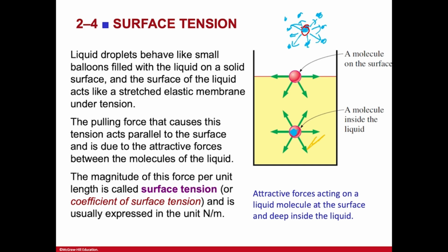So as a result, if you try to find the net force acting on this fluid molecule, what will you get? If you try to resolve all of the forces into normal and tangential components, you'll see the net force acting normally, upwards and downwards, will be equal, so it will balance and cancel out, and the same thing in the x and y direction, so left and right. So essentially you will have zero net force acting on it because of how uniformly all the molecules are interacting with that particular fluid molecule.